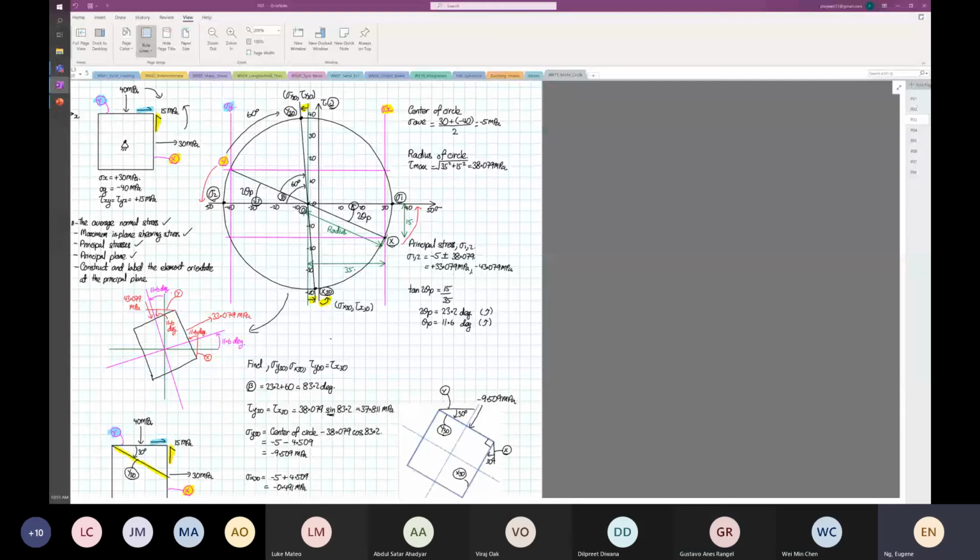So for Y30 to rotate in the clockwise direction, the shear has to be coming down this way. Can you see how I draw the shear on the bottom right hand column? The Y30 with the shear in this direction, the element will rotate in a clockwise direction.